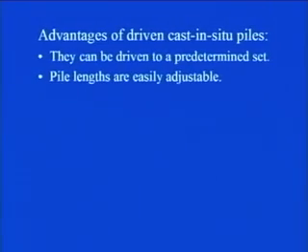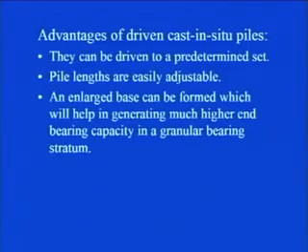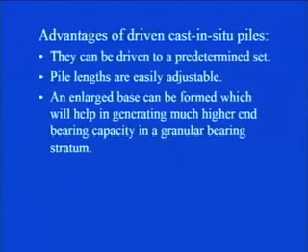So, let us say at the 11th hour you change the length of the pile, then that can be taken care of. An enlarged base can be formed which will help in generating much higher end bearing capacity in a granular bearing stratum. Let us say that you are driving a pile in a granular bearing stratum. Then towards the end of the pile, where its tip will be resting, there you can provide an enlarged base which will result in larger bearing capacity. This aspect also we discussed in the last class.